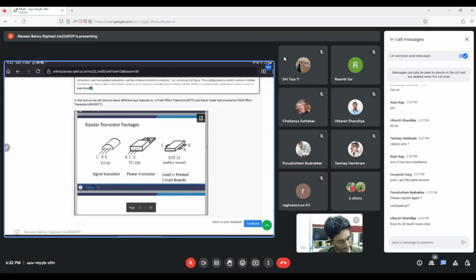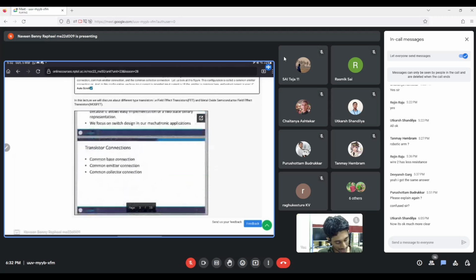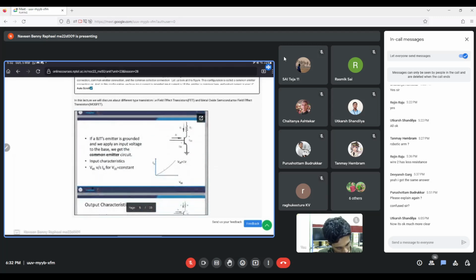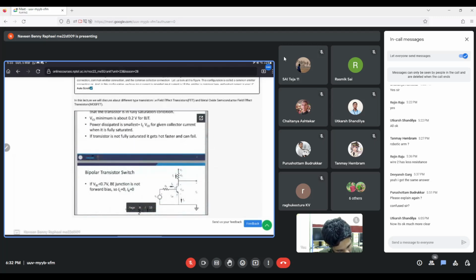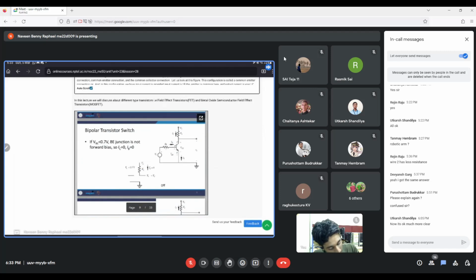Transistors are used as switches, as explained in the first few slides. You can use a transistor as a switch, as evidenced by this section. Essentially, if you provide a current here, it conducts; if you don't provide a current here, the voltage across VCE won't allow current to pass through. Therefore, it acts like a switch. I prefer if people ask questions regarding this.